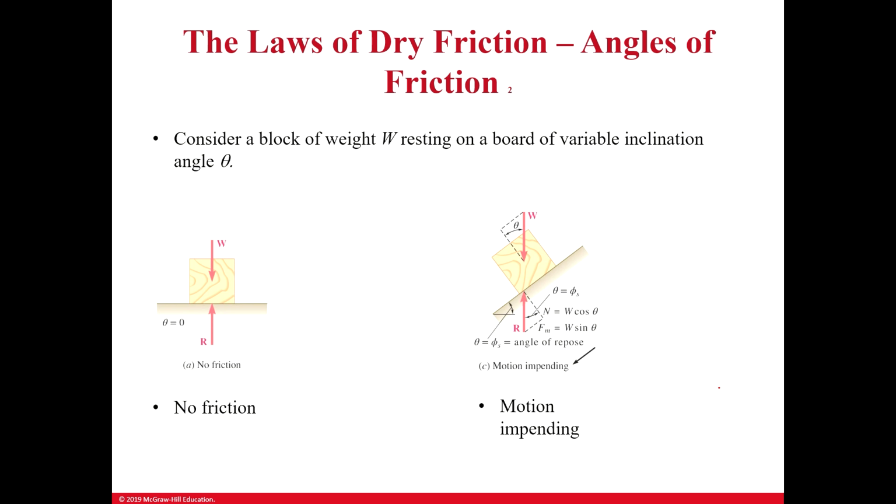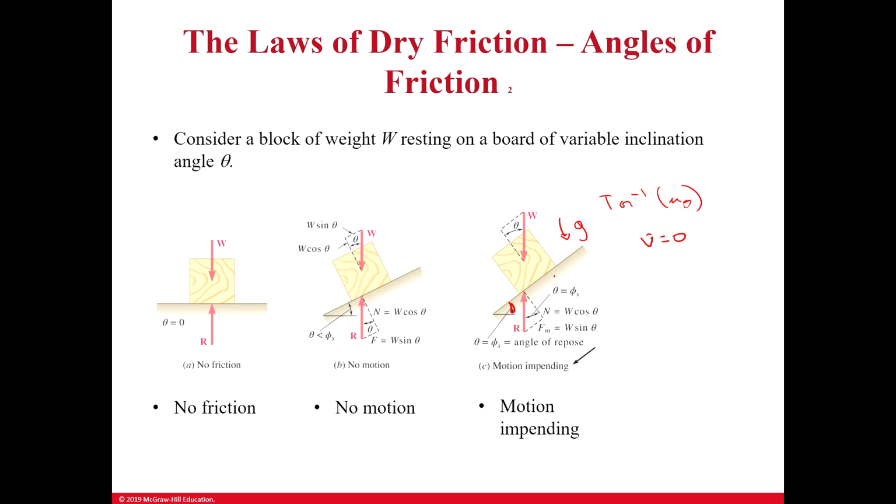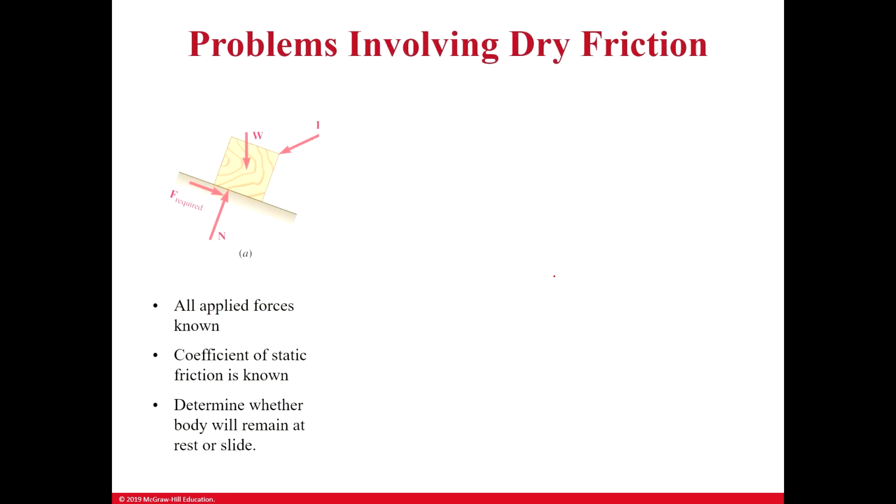All right. So as I said, that angle right here, sometimes if you have that angle being the same as the tangent inverse of your static friction, up until that point, you have velocity equals 0. If your angle is greater, then you can have movement just because of gravity. So now we're going to start taking into account gravity as well. It's just these different concepts of how to set up your system, your coordinate system.